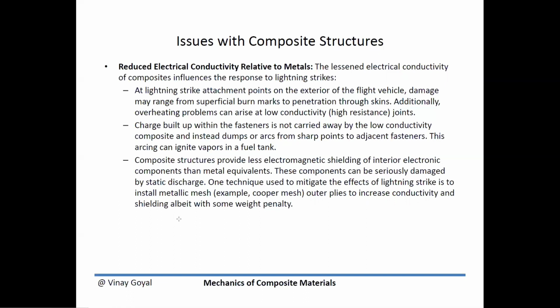And so I already talked about the overheating issues, but charge built up within the fasteners is not carried away by the low conductivity of the composite, and instead you could have some sparking that could ignite some vapors that could become flammable, or it could ignite in a fuel tank.